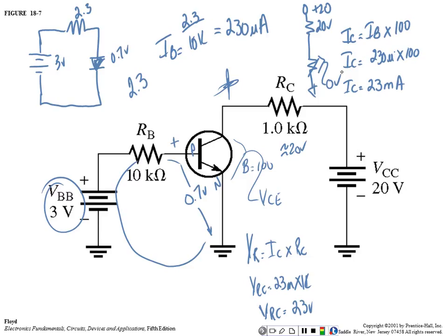Yeah, 0 volts, so the transistor's saturated. Of course, this is not going to be true. The transistor's going to drop less than a volt, and the rest will drop across your resistor. So if you calculate IC, multiply it times your collector resistor, and come up with more voltage than is applied, we cannot drop more voltage than is applied in a circuit. So the transistor is saturated.